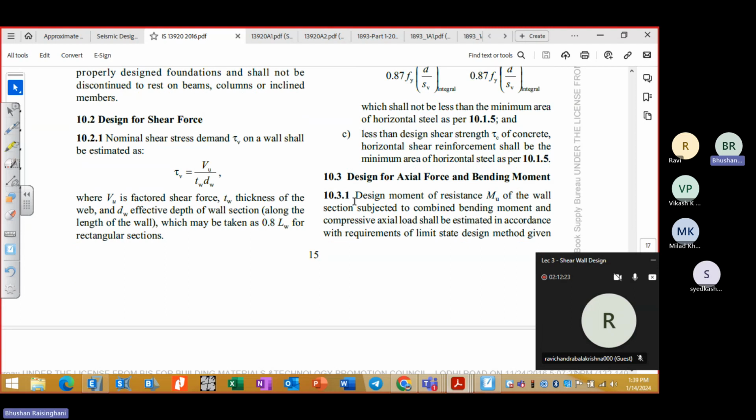The next part is related to axial force and bending moment. So every shear wall has a PMM interaction curve. So P-M1 and P-M2, okay, the interaction curve you will get from the software. Same, you can also make your PMM interaction curve if you want for the rectangular shear wall. And development of those PMM interaction curves requires a formula and neutral axis depth. So based on that you have to develop the PMM interaction curve, and you can compare it with the software.